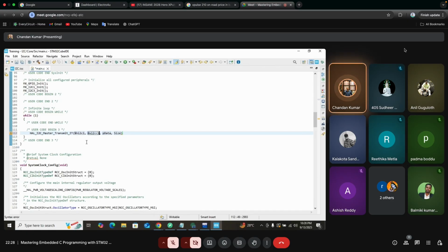Whenever you want to read registers, it will be given in the data sheet. In some data sheets and ICs, when you read the data sheet, it will say that if you want to read its device ID, you will have to left shift or right shift its register by 8 bits.